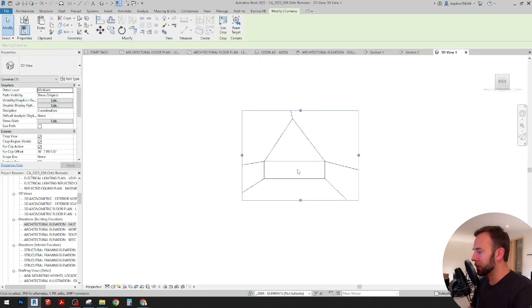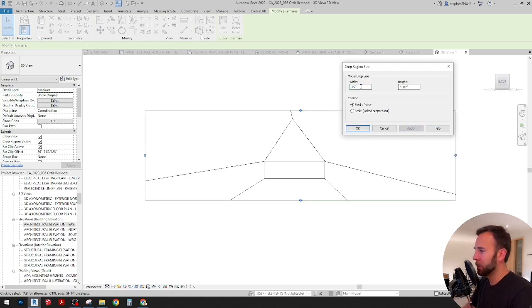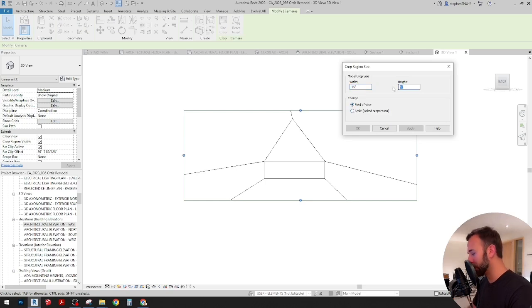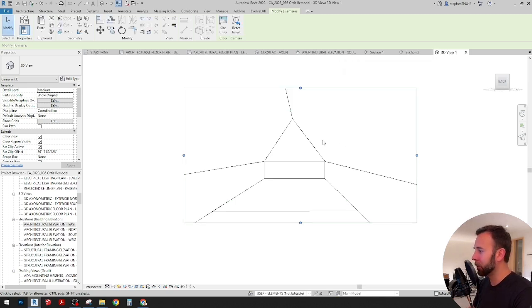And it's looking pretty basic, so the first thing I like to do is extend the width. In the field of view, do about 12 inches, and then scale that to 16. Oops. And after it's scaled to 16, then change the field of view also on the height. And that should give you a 16 by 9 view, which is great for rendering. And it should be about a 90-degree field of view.